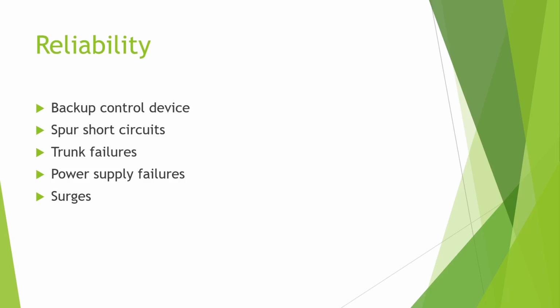Right? So soft start means we're going to ramp it up to full power, not just be like contactor clunk. Full power just surges right to that motor. A motor is basically a dead short, if you think about it, right? It's just a wire that wraps around a whole bunch of things and comes back. So when you turn a motor on, it's got a dead short.